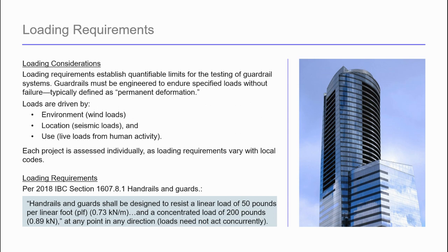That's simply the forces that are required to be applied to a railing that that railing must resist. They come from things like gravity or dead loads, human activity, live loads, which are the most important for railing, and the environment: seismic, wind, snow, temperature. Live loads or wind loads on exterior structures almost always determine the construction of railing. Seismic loads can occasionally affect design in high seismic regions such as California. Temperature loads are caused by expansion or contraction of the railing due to changes in temperature.